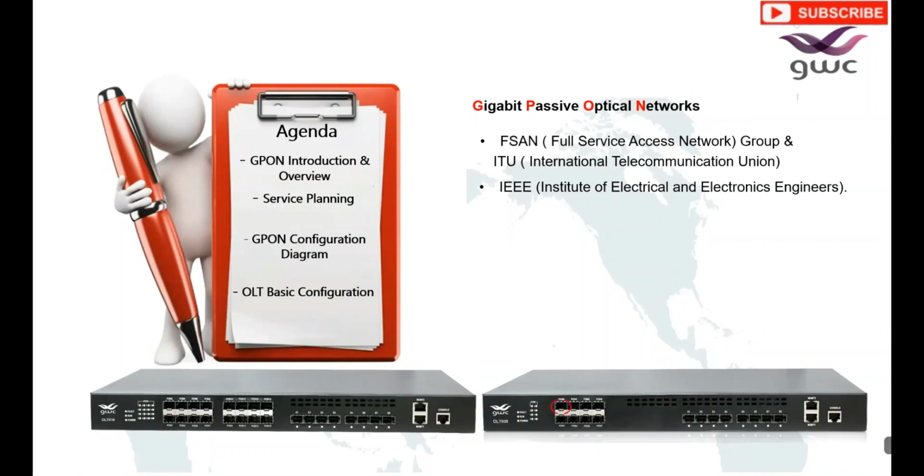The benefit of using a PON network solution is that the typical split of a single fiber is 1:32 or 1:64, which means each fiber can serve up to 32 or 64 subscribers. Split ratios up to 1:128 are possible in some systems. Lower cost by up to 70%, less power by up to 80%, and less space for device installation. Instead of buying multiple switches for the network, you can have GPON cover up to 1024 devices for FTTH, fiber to the home, on a single OLT 008.